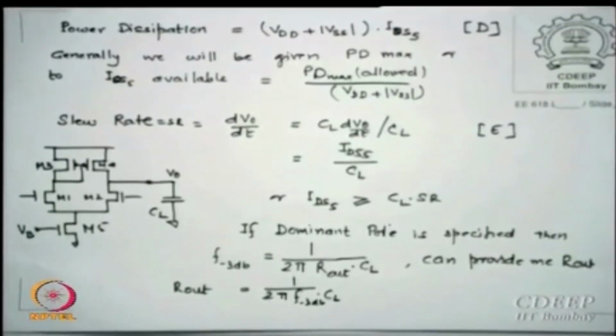So essentially it is decided by the change in temperature of the device, and we know that around 150 degrees plus the junction loses its junction property, and because of that no junction will remain a junction. The leakage current will go so high that diffusion current will be dominated by drift currents. So we want to avoid that situation. So what do we do then? How do I decide that?